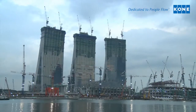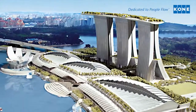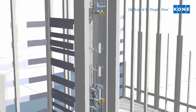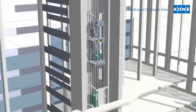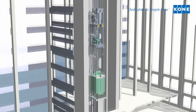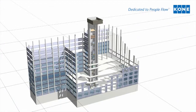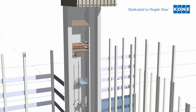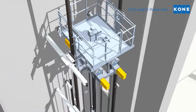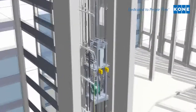For example, in this project, Marina Bay Sands, Singapore, the builder used 13 jump lifts to meet the challenging construction schedule. What makes the jump lift unique is the moving machine room that jumps upward when the building grows. Kone Jump Lift is self-climbing, so it does not need a crane to do the jump. The jump height is typically 2 to 3 floors at a time, so it can serve all the floors to the top minus 2. The jump can be completed overnight to reduce the service break.